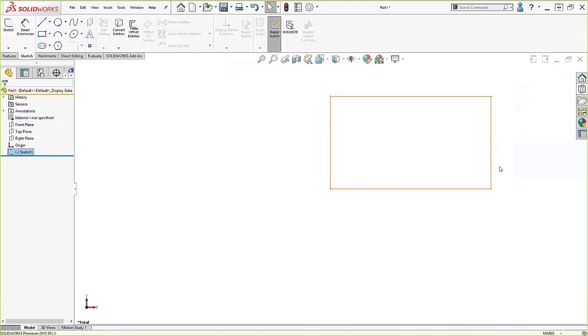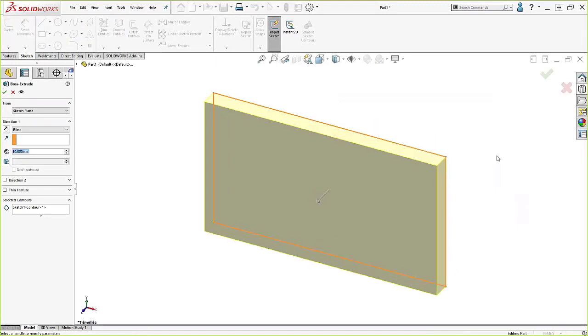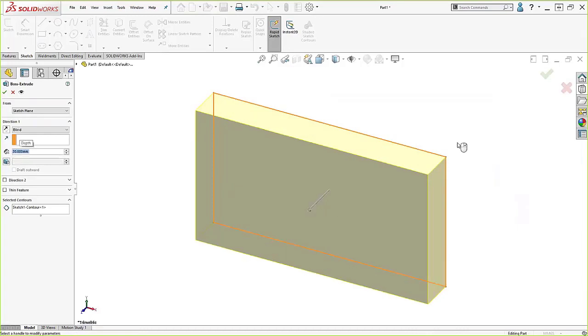Got a part here. All of these enhancements, I'm going to show you how quickly I'm able to use these. But here's the deal with the mouse pointer feedback, okay? When I finish my input to this extrude, I want you to pay attention to that little icon that's next to my pointer. Let me do it again. We'll bring it back up. Can you see that? That's right there next to my pointer. That's a little check mark. That means if I right-click now, I'll finish my process.